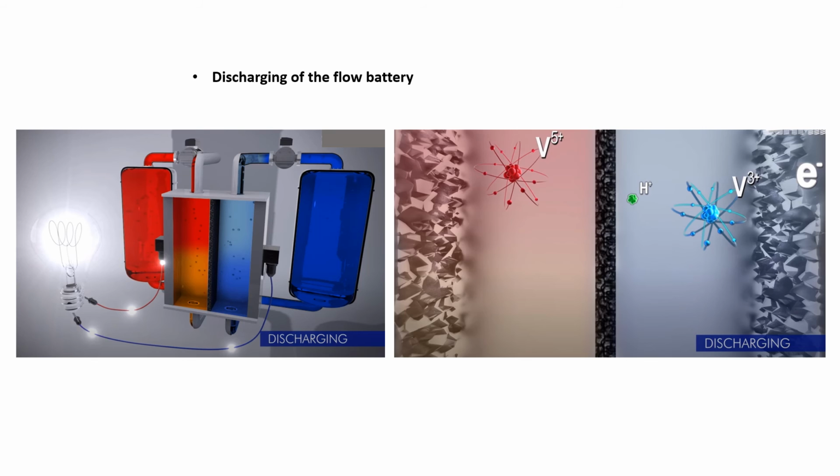Flow batteries can be independently scaled for appropriate power and energy, and the power can be adjusted by increasing the cell size, the number of cells, and expanding the tank volume to meet the requirements. The main advantage of such flow batteries is that there is negligible or no loss in power capacity due to side reactions beside the main electrochemical reactions, as observed in conventional batteries, and the lifetime is longer than any other storage system. Even the deepest discharge does not influence the battery health.